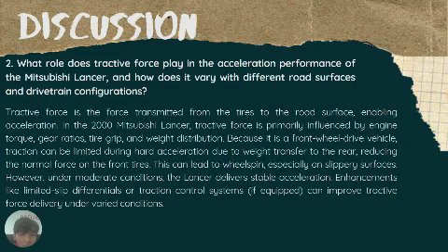Because it is a front-wheel drive vehicle, traction can be limited during hard acceleration due to weight transfer to the rear, reducing the normal force on the front tires. This can lead to wheel spin, especially on slippery surfaces. However, under moderate conditions, the Lancer delivers stable acceleration. A limited slip differential or traction control system, if equipped, can improve tractive force delivery under varied conditions.